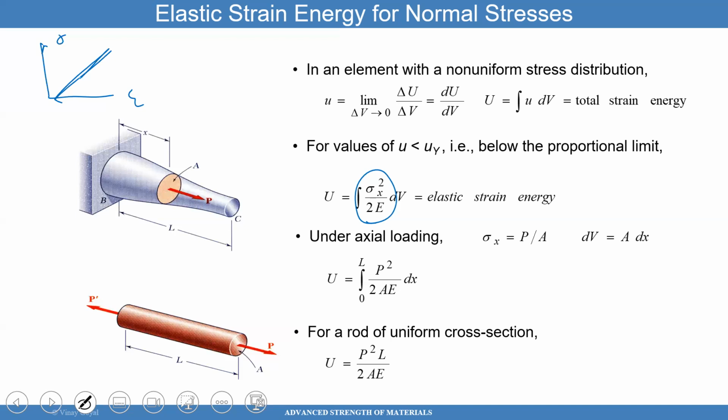What is the area under the curve of that stress strain curve? 1/2. So the energy is 1/2 sigma, the stress, times epsilon, correct? Now you can write this in terms of stress, or you can write it in terms of strain, right? So what is strain in terms of stress, as an example? Strain is equal to stress divided by modulus. You agree? That's one way. So that's 1/2 sigma squared divided by E, which is exactly what you see there.